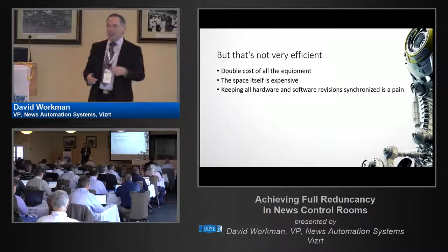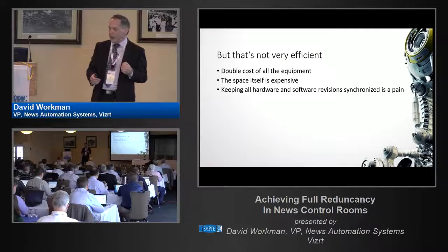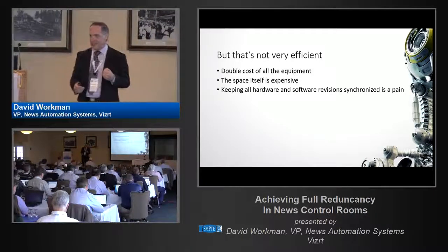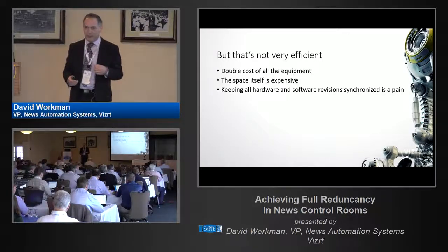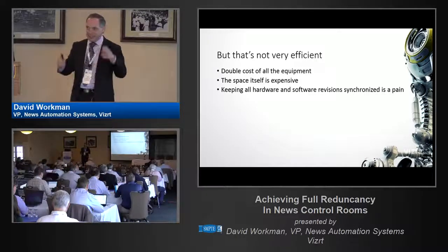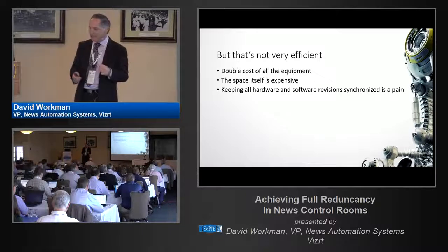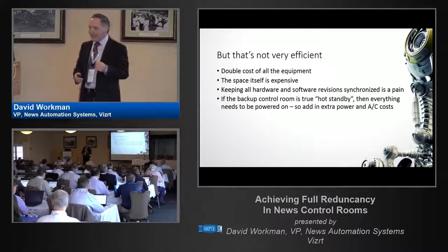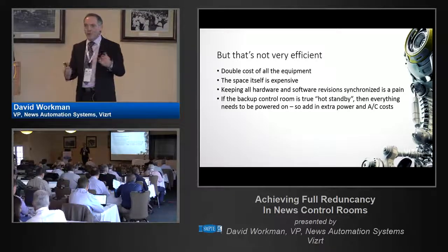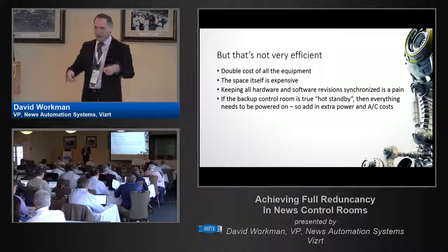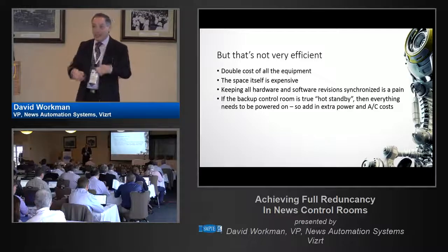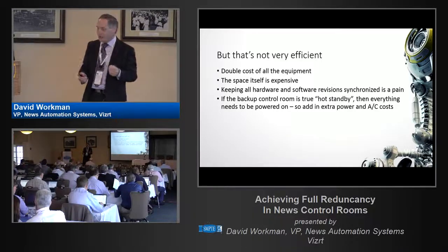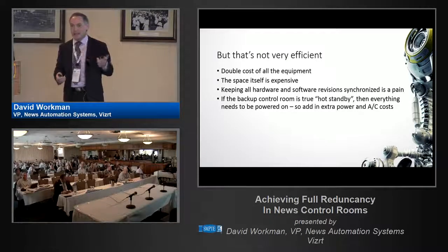And then from an engineering standpoint, keeping all of the hardware and software revisions synchronized, keeping all the updates and patches applied, making sure that everything is operating at exactly the same level is a pain. And if you really want it to be a true hot standby, meaning that if your main control room goes down and you have to run over to the backup control room, it's got to be powered on and running all the time. So you have your extra power and AC costs and everything else on top of that.